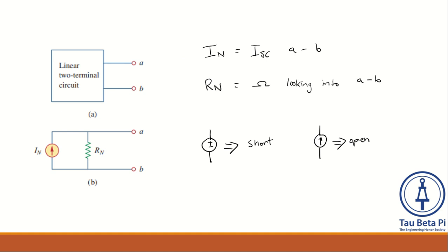So what does that mean exactly? Whenever we have a Norton equivalent circuit, we think of that equivalent circuit as this kind of box, an abstracted circuit. We don't really care how complex the circuit is. All we care about is the characteristics that the circuit has. And in the Norton equivalent circuit case, we understand it to be a current source driving a parallel resistor and whatever load resistance we may choose to hook up to that circuit.